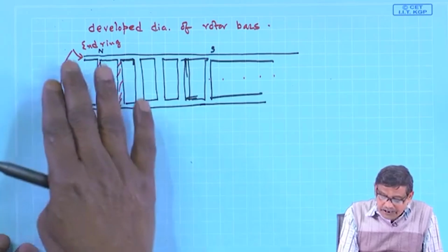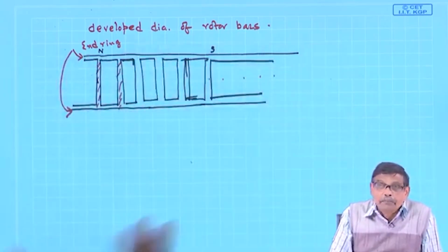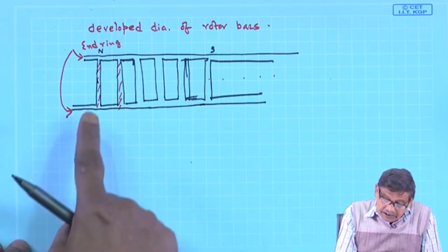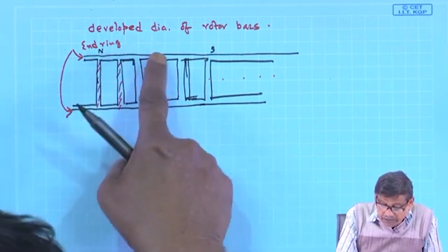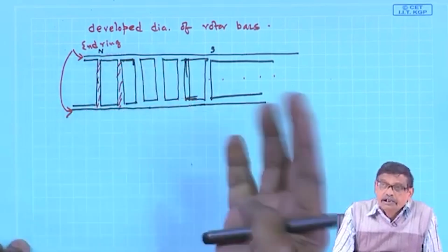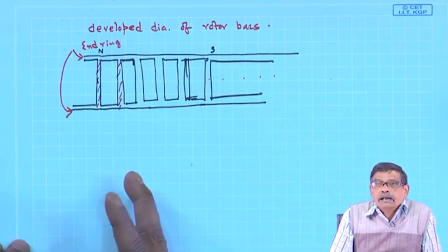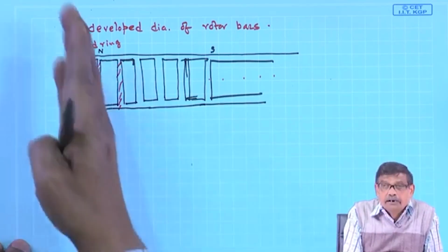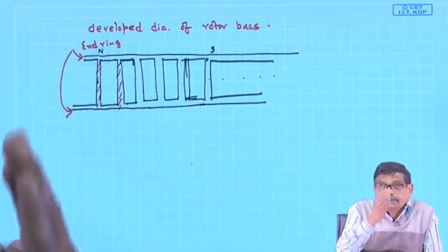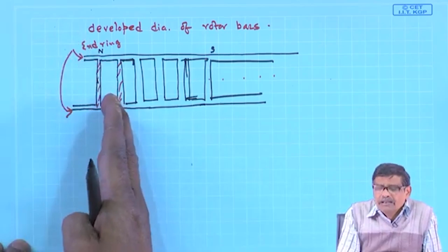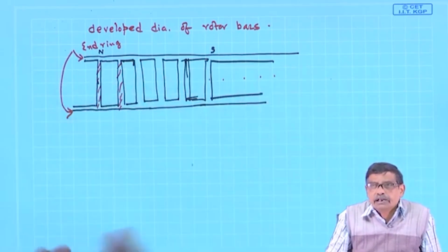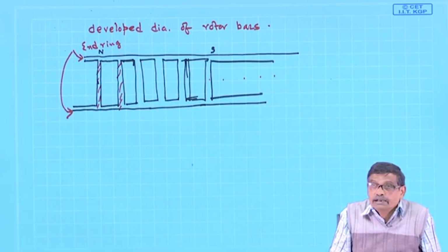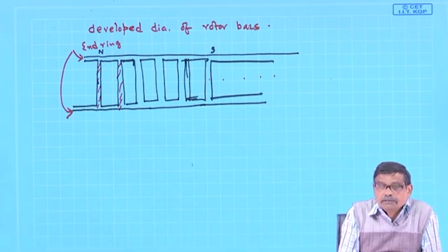That is the beauty. It is already shorted, but in a slip ring induction motor that is not possible, because the return conductor of a particular turn is already decided by me, and I have taken all the care that if one coil side is under the center of the north pole, generally the other coil side will be under the center of the south pole, and they have got their own identity, a separate coil.